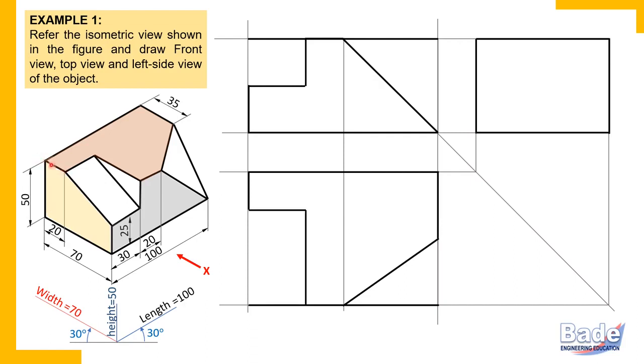Now this is one more principal edge which is 20 millimeter. So measure 20 millimeters. Better to measure 20 millimeters independently. But otherwise, this 20 millimeter long edge is common for this surface and this surface. So this edge we have already drawn here, 20 millimeter long. So you can project this edge here in the side view by drawing projectors in this manner.